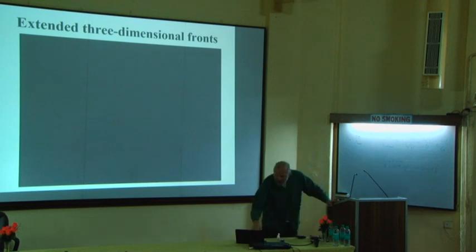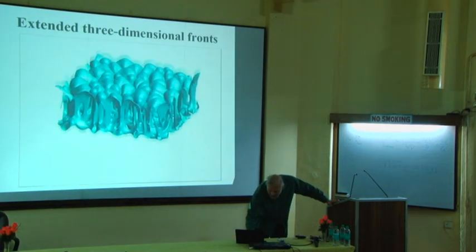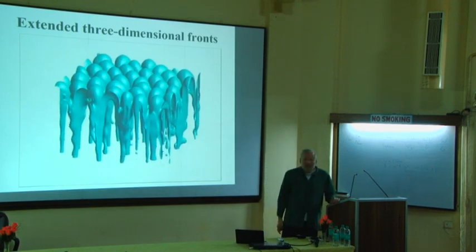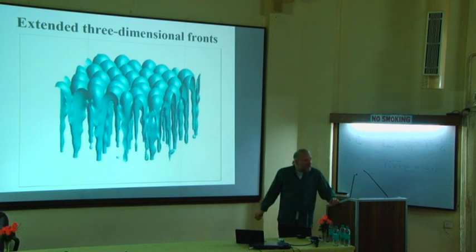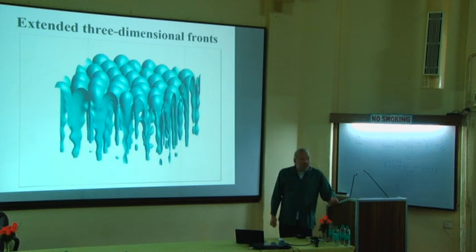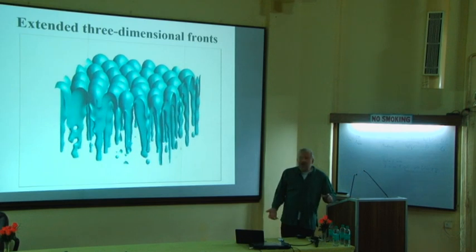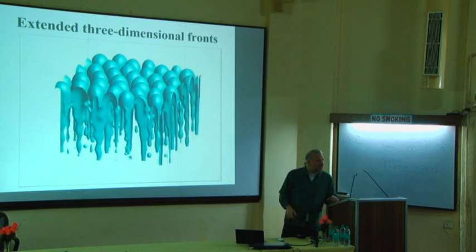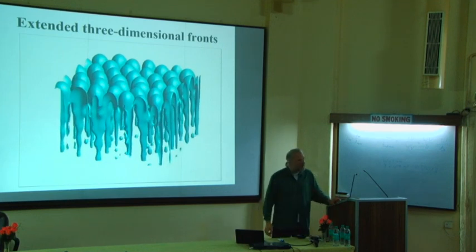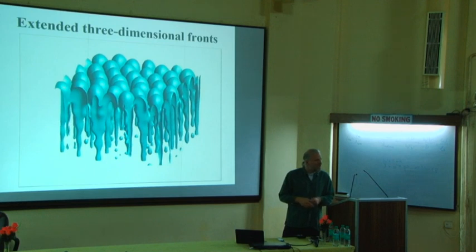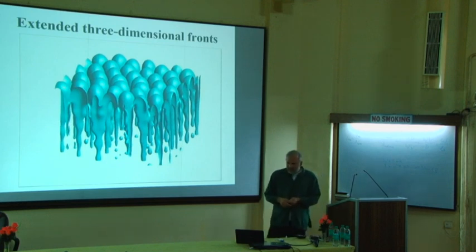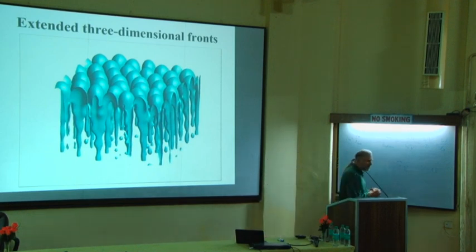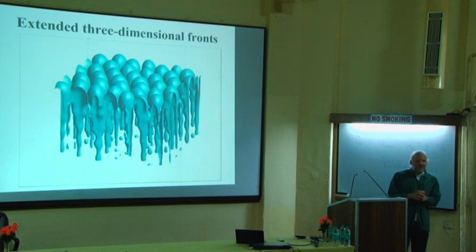Now here, my simulation box, for this three-dimensional simulation, the cross-section was 240 by 240 grid points. Typically, one solidification cell is 100 microns in diameter. So with a reasonable computational effort, you can simulate a system that is almost 1 millimeter squared in section. So this starts to be a scale where you can do really interesting things for metallurgy. Okay? So this is the end of the part on the alloy phase field models.